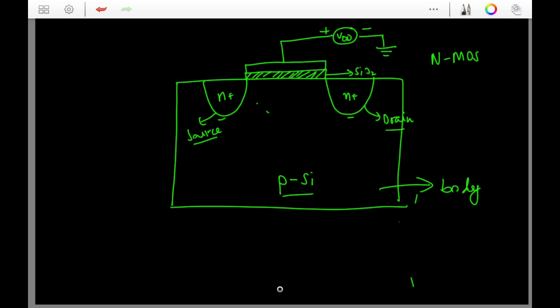So how do we do that? This is where the MOS comes in. The MOS conducts current through an electron channel. Let me repeat that, it conducts through an electron channel. Now, you might be asking that since the body is a P substrate region, and if the current has to flow from source to drain, it must do so through holes. So where do the electrons come in? Well, this is what is special about the MOSFET.